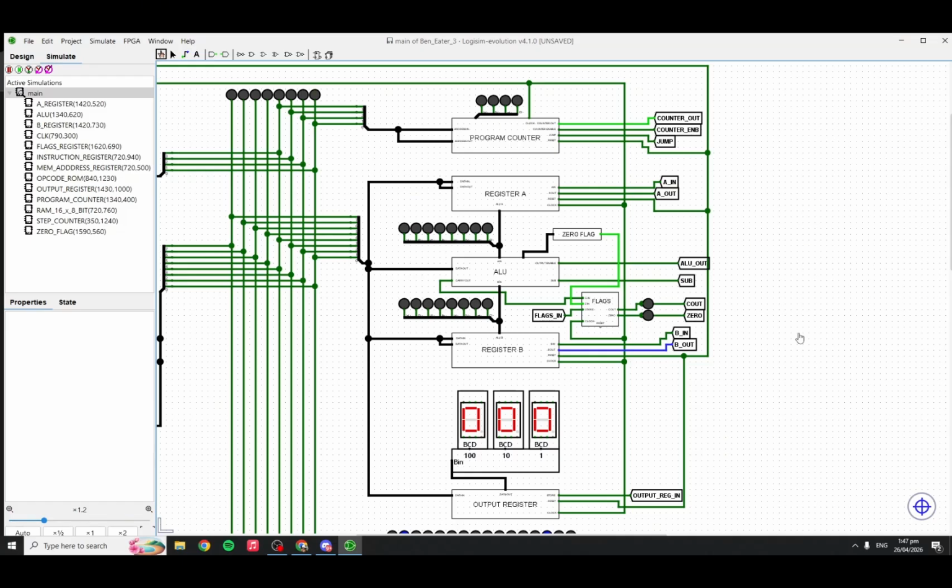As the sequence grows, the values increase rapidly since the system is limited to 8 bits. Once the result exceeds 255, an overflow occurs. At that point, the carry flag is set to 1. The control unit detects this carry flag and executes a conditional jump instruction such as JC, which then resets the program back to the beginning. This allows the Fibonacci sequence to restart and run continuously.